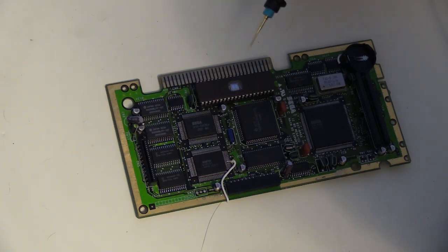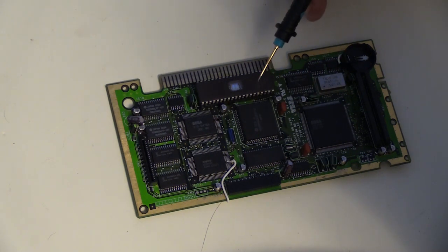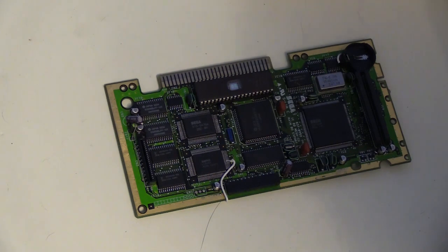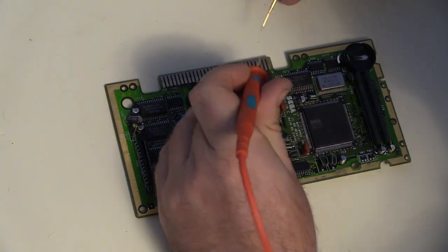Whereas we were seeing a boot failure in part 1, we were able to see that the 68000 processor on the Genesis was reading garbage code over this edge connector, and so it wasn't booting up properly. And since this EPROM is responsible for feeding code to the Genesis, that's where we're going to focus our efforts. I did verify that this EPROM contains a valid BIOS. I even programmed a fresh EPROM with the code just to make sure that it wasn't a bad EPROM. Still had the same problem. So let's go ahead and step through this.